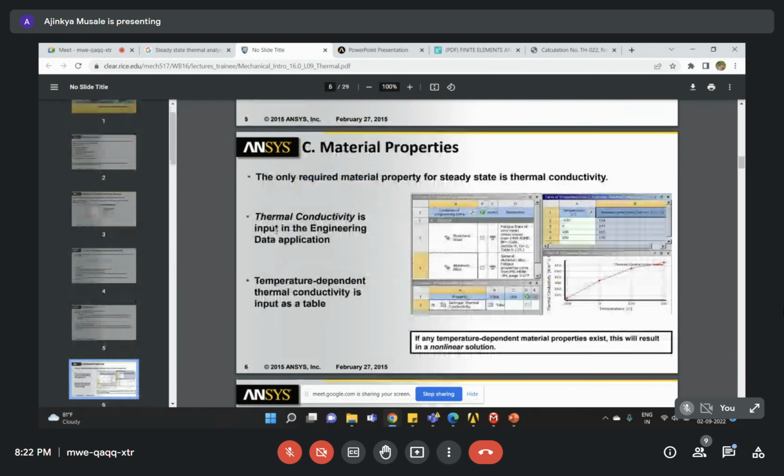Fine. Here, the materials are what we defined for our structural calculations. The only difference between that material and this one is the isotropic thermal conductivity. That part is additional. It wasn't used during my structural calculations, even if it was present. But in this thermal calculation, this value is very important.